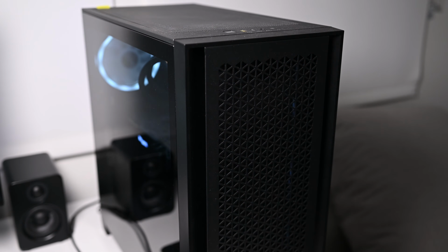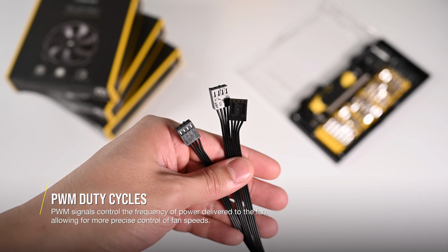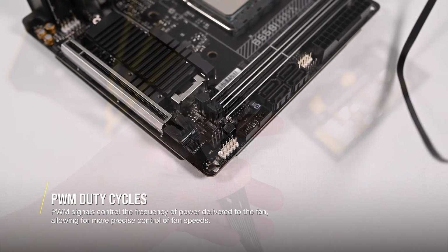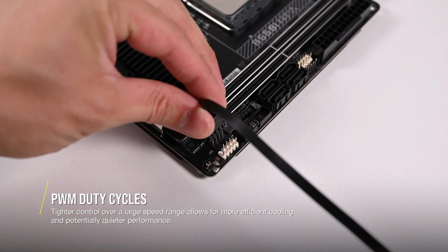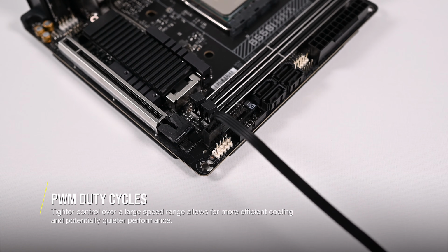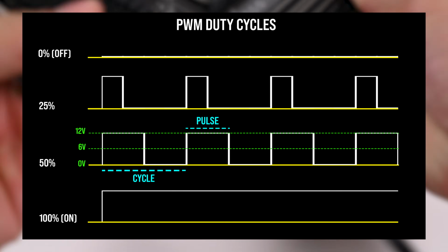PWM fans will come with 4-pin connectors instead of 3. The 4th pin on the connector is what provides the control signal for a PWM fan. How PWM controls voltage delivery is measured in Hertz and is typically represented as a percentage or duty cycles. The lower the duty cycle, the lower the RPM on the fans.